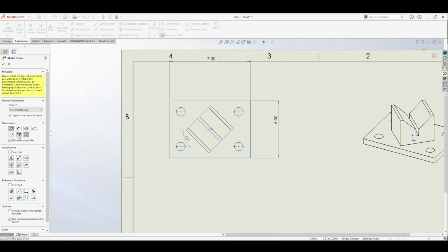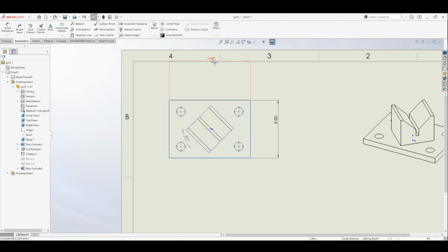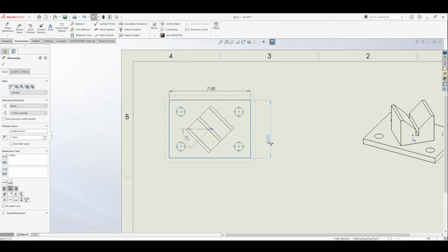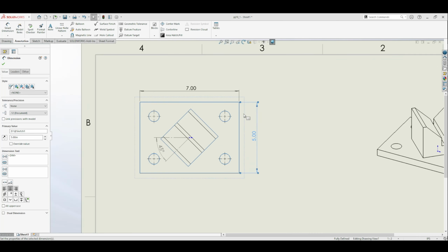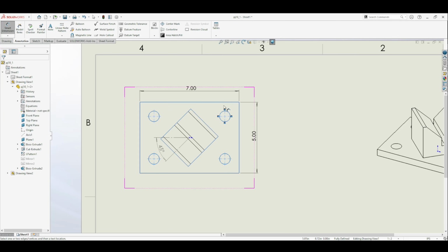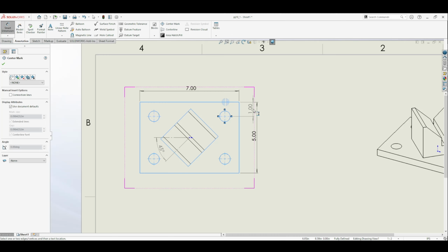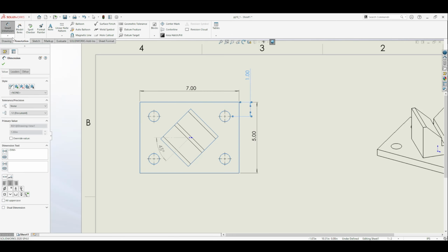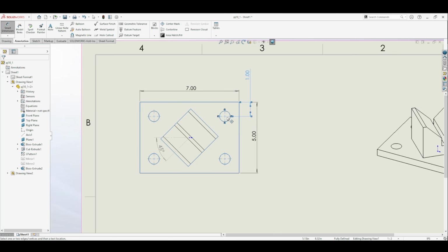And so that didn't show us the whole details. So we can just do that for right now. So that gives us that width, and that gives us that width. We want to show that dimension to here, except it's showing an angle. So let's try to force it to show us that distance. So that's a vertical dimension, and the horizontal dimension is that 1 and 1.